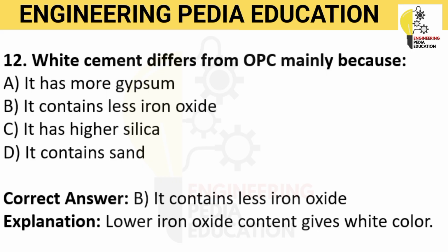Common uses of white cement are also wall finishing, tile grouting, decorative flooring, architectural design, and putty manufacturing. White cement differs from OPC mainly in color, raw material composition, and decorative application. White cement contains very low iron oxide, giving it a white appearance.